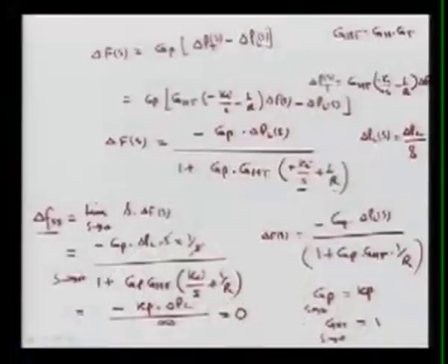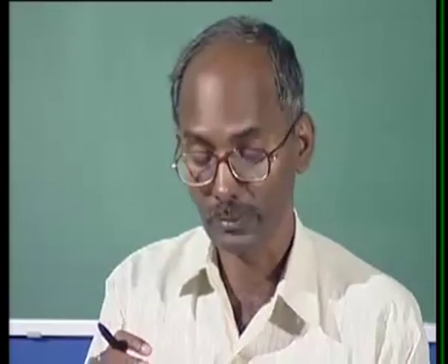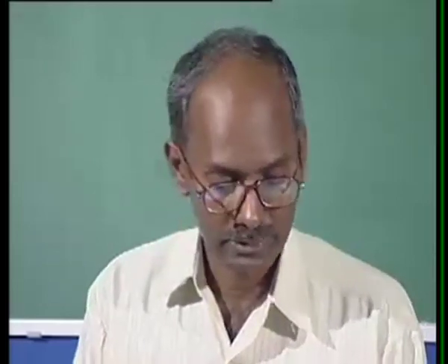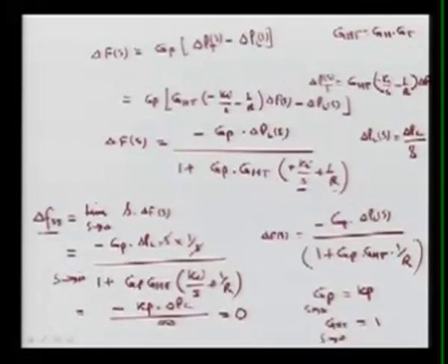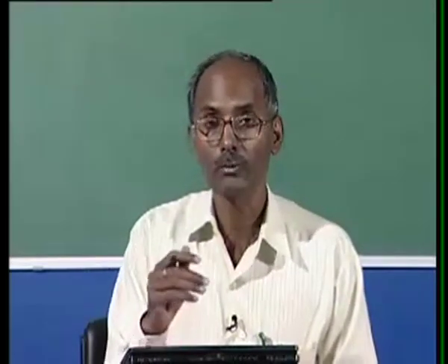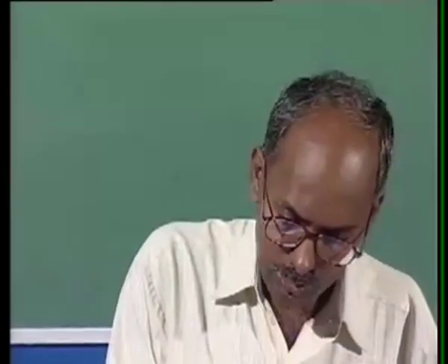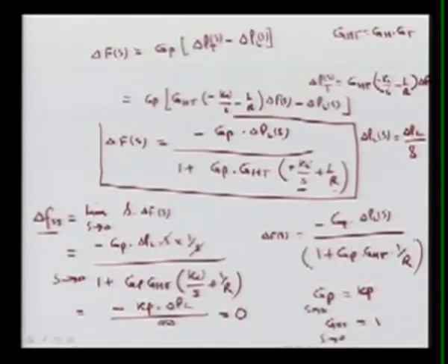So this is your steady state response of this whole secondary ALFC, that is, secondary area automatic load frequency control. Similarly, we can go for the dynamic performance, and we'll see that Ki plays a very important role in the performance of the dynamic response. So here this is the complete closed loop transfer function, for which we saw the static performance, and the steady state we found is 0, and that was required.